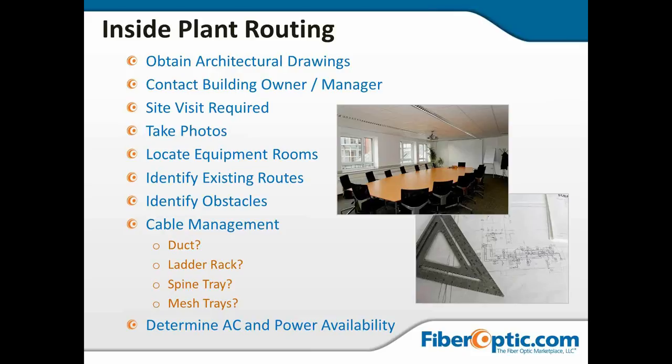And then you want to look at your air conditioning and power availability in all of the cabinets and all of the places that you're going to need to have active devices. If you've got a powered switch designed in the ceiling space, you've got to make sure that you've got power there to turn it on.